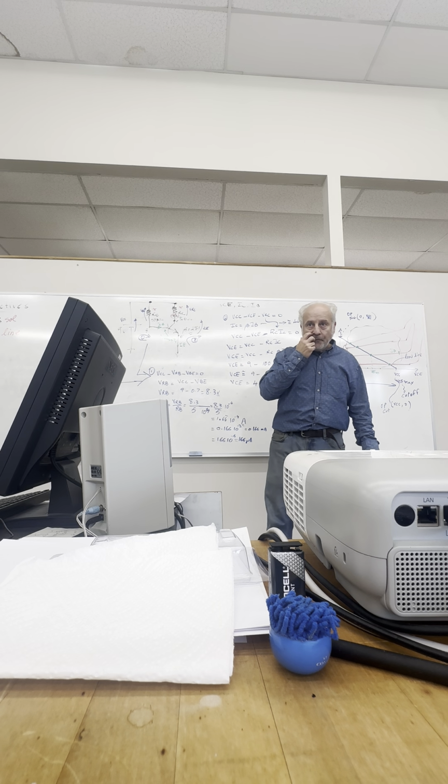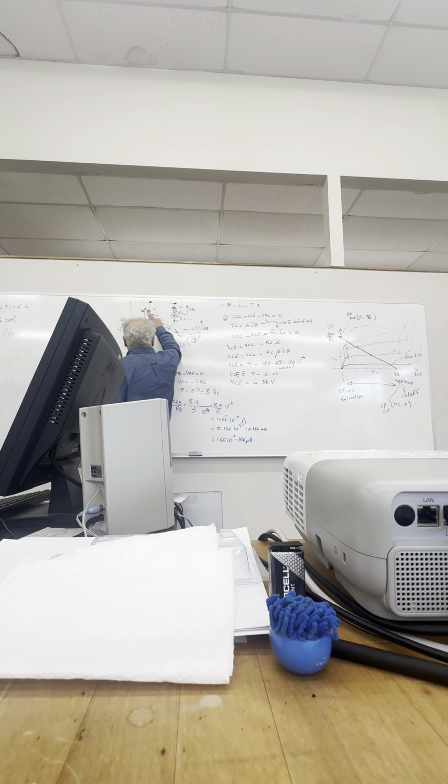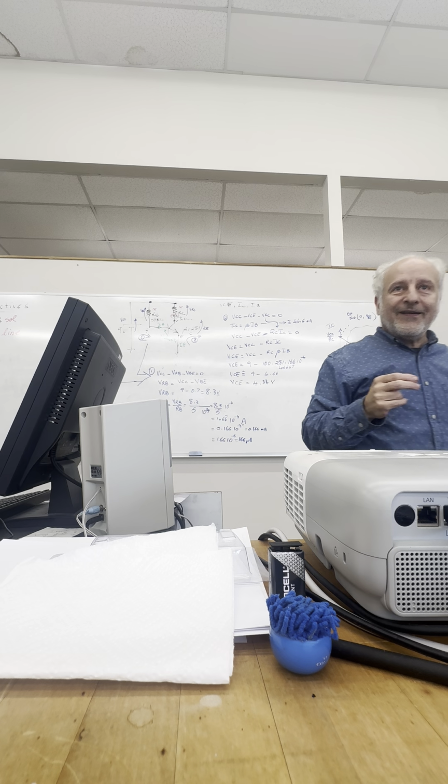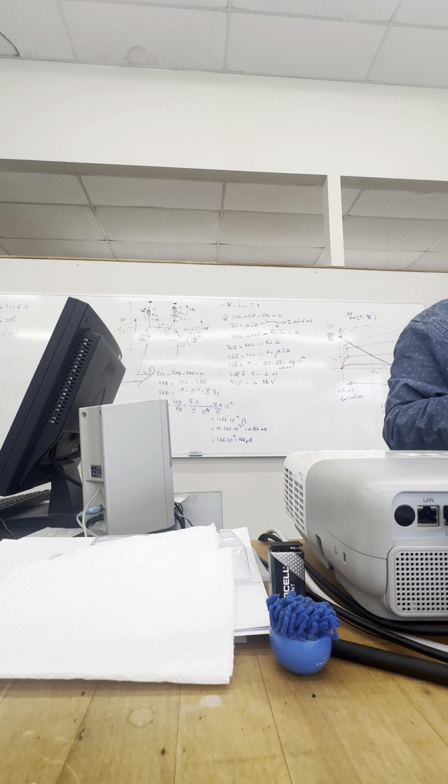Okay? And the beauty about this, you don't need a lot of current here. So your potentiometer will not overheat. It will be nice and it won't spark. Does that make sense? Which you want, because any time where you have hands anywhere, you want as low current as possible. And the base of a transistor offers you that.